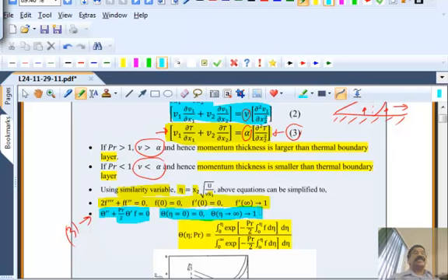It's a second order equation. It's a linear equation, but it involves f as an input. So the velocity profile must be obtained first, which is given in the form of the Blasius solution. It's in tabular form. So take the table, put it in there. You can integrate that numerically if you choose to. But we also saw that we could integrate that analytically, and we obtained the solution as given in here. Except to note that this f is tabulated. So we need to evaluate this integral that you see here numerically, as a quadrature.